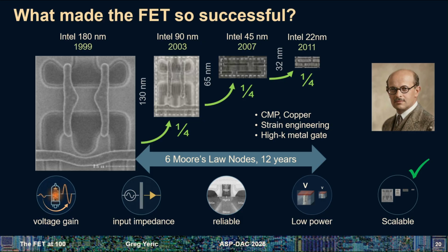Switching from aluminum to copper, from a resistance and reliability standpoint, copper, you can't etch it chemically very well. So we went to a chemical mechanical polishing, CMP, damascene process to make the copper, and that's all kinds of yield and reliability problems. People actually shipped copper parts in the early days of copper that failed at the customer sites because of things we couldn't foresee, had to improve the processes. Strain engineering, we're definitely going to talk about that. As we shrunk the transistors, we kind of ran out of performance for various reasons that we'll sure talk about in the class.